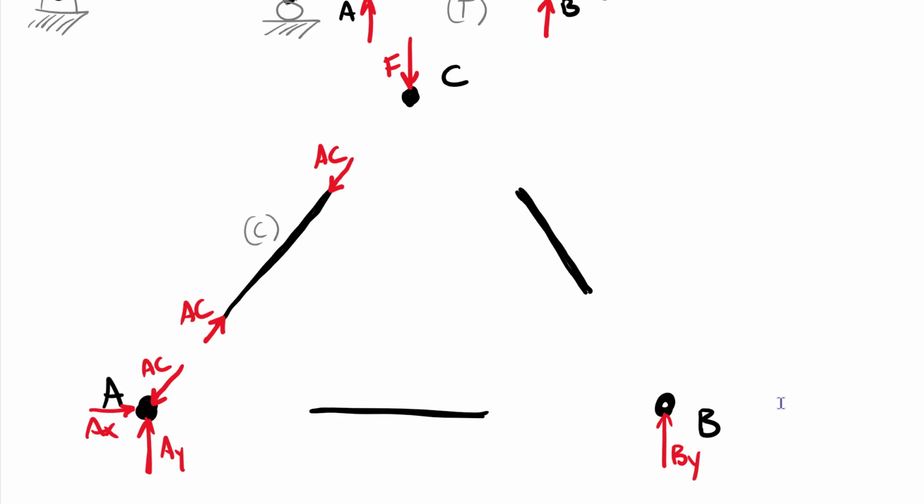Let's do the same thing over here for BC, a force pushing, squeezing that together in compression. So we have basically unknown forces on either end, but the magnitudes have to be equal because it's a 2-force member. I didn't quite get this perfectly in line, but that'll work out all right. So here is BC in compression and another BC in compression.